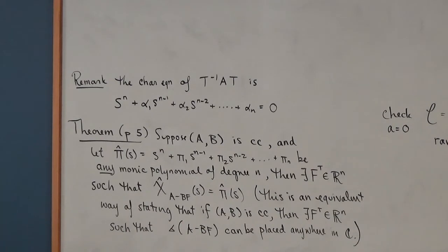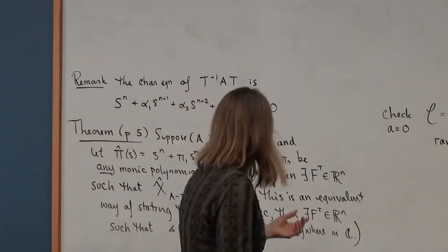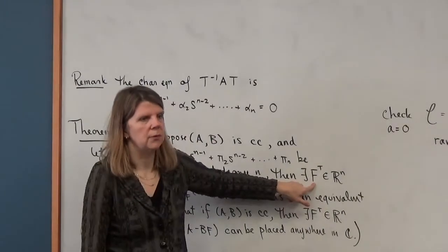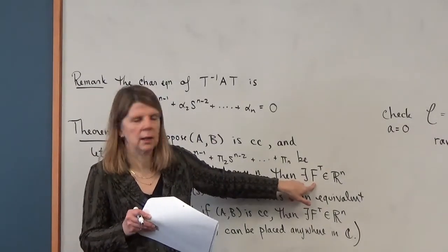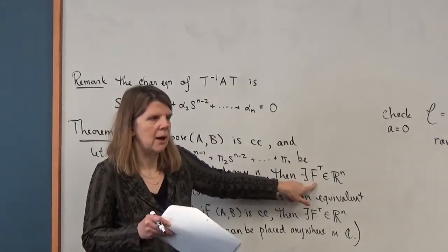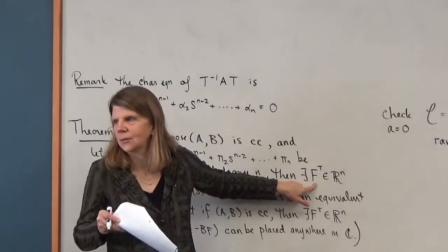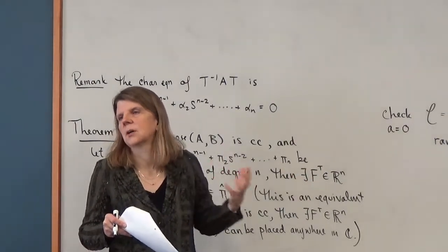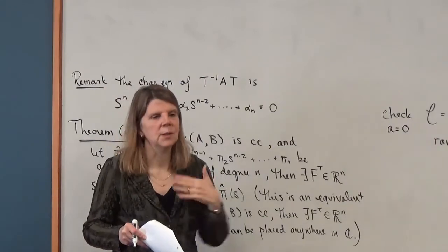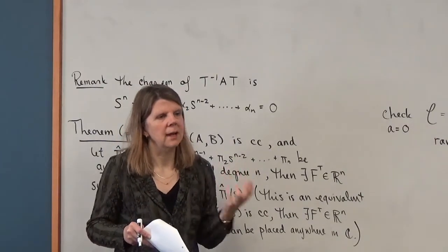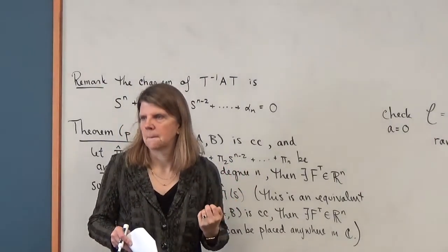Control effort. So if you're going to try to move every single eigenvalue, F is going to have to provide action on all of those eigenvalues. So it typically means you get a bigger matrix F in your feedback path. And what does bigger gain in your feedback path result in?